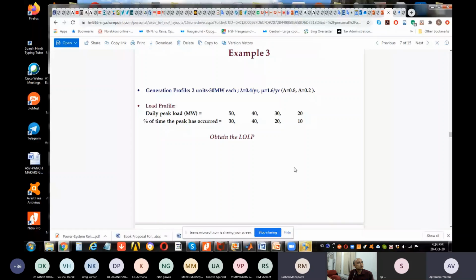That is a US military standard, which is 1629A. So I think if you happen to go through it, it will tell you how to conduct this failure mode effects analysis. And of course, there are many other standards also which tell you that. But since most of this approach has basically originated from the US Department of Defense, they have military handbooks and standards. So 1629A refers to the failure mode effects analysis.